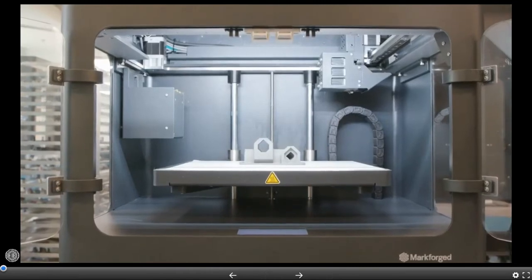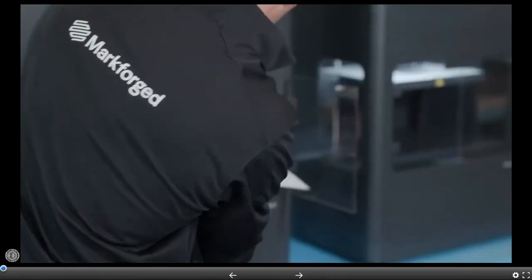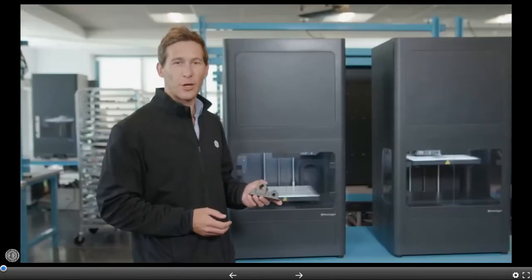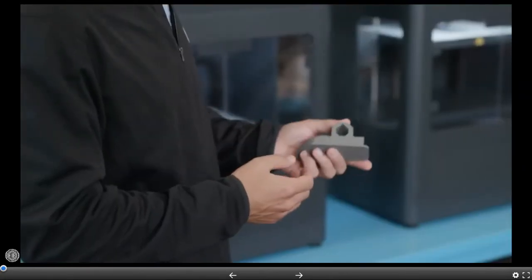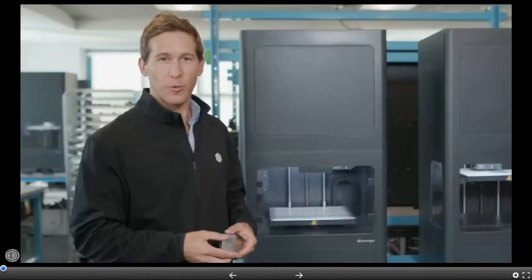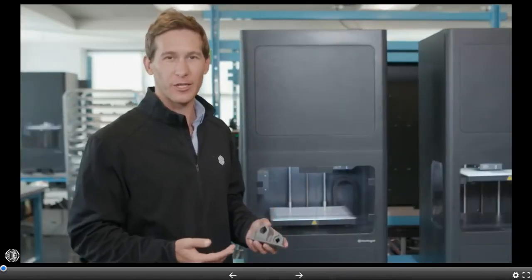Once your part is finished printing, you'll get a notification. At this point, you can go to the printer, remove the part from the build tray, and clear the bed. Now we have what's called a green part. It doesn't really look or feel like metal. However, a large part of it is comprised of metal powder. Next step will be putting it into Wash 1 for the debind process.